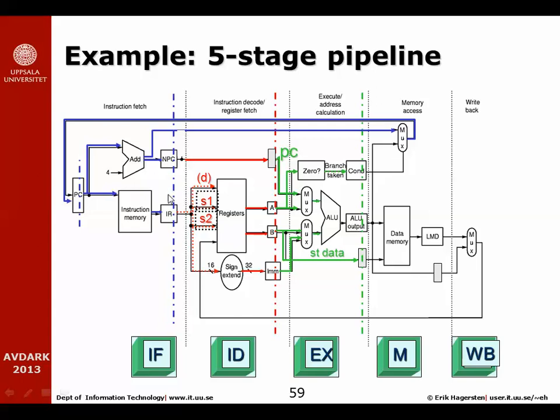So these bits here that we stored at this point in time, even though it's not shown in this picture, some of those bits also travel with the instruction, and at this point in time a special set of those bits will be used to choose this mux, saying if this is a branch we're going to try to calculate the next address for, we need the PC value here, otherwise we can't make that calculation. If this is the type of instruction that has an immediate in it instead of 2 source register values, then this mux here will get a special signal that is carried all the way from over here that will control it to take the lower input of the 2 and input the immediate. Otherwise, it will input the value we got out from the other source register and put that into the ALU. So that is to make sure we get the right data to the ALU.